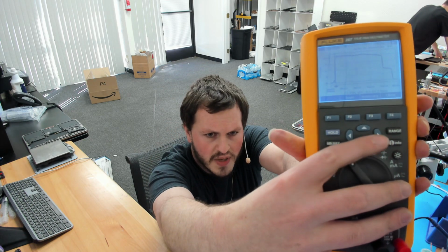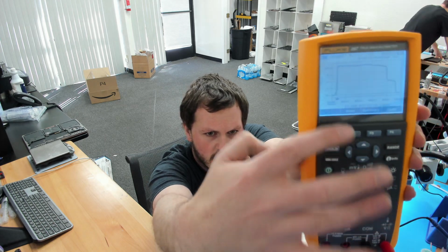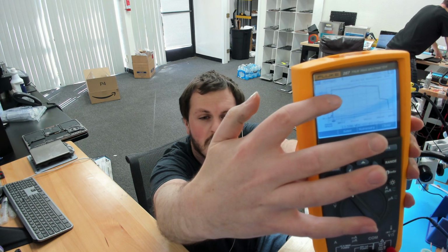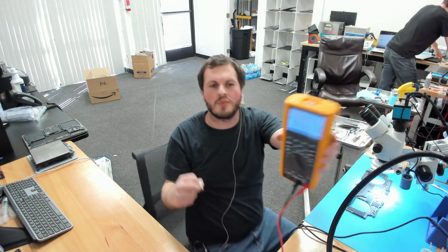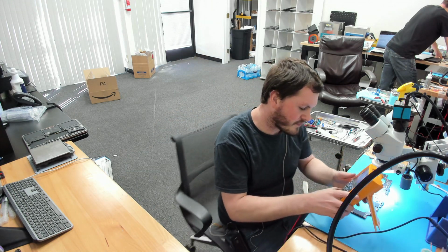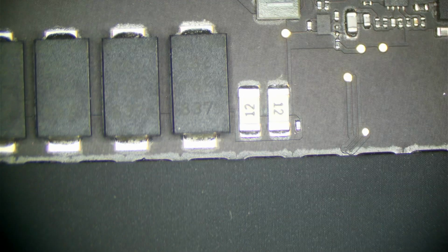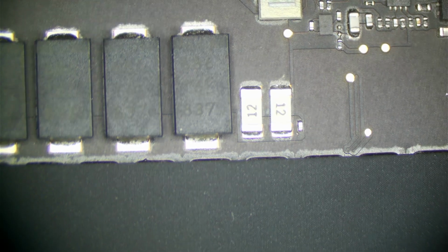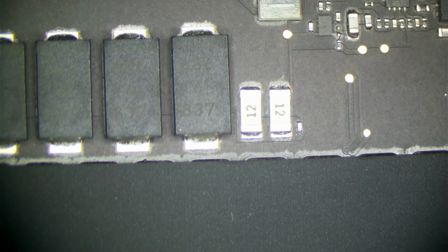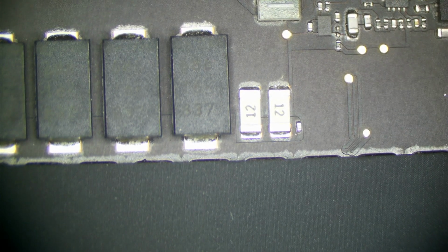So I'm going to try my best here to show you guys, but there was a drop right about right there. It just drops down to 12.2 for a brief second, comes back up. So that's interesting. Something's going on in our T2 circuit. So something is definitely amiss there. So let's check. I'm just going to start checking common things that I have seen before.